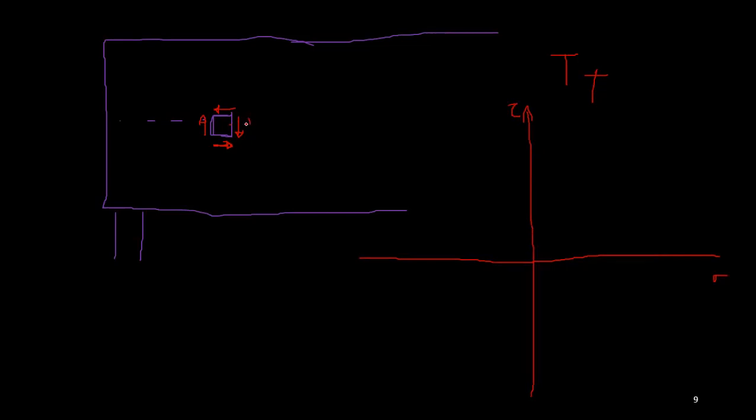Why? Because you don't have any bending stress, right? Bending stresses are normal, right? Those are maximum at edge fibers and becoming zero at the neutral axis. So if you consider the neutral axis, bending stresses are zero. So that means you do not have any normal stress on this element, right?